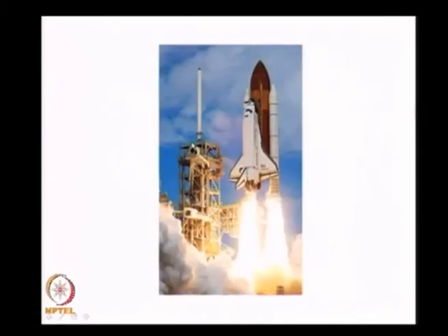At the bottom on the right hand side, the opening opens out, some flame comes out, and when this flame comes out, it hits against one of the attachments which is attaching this to the main rocket, and that gives way, and this fellow comes out and it gives a thrust in some other direction. Not only that, this flame hits against the hydrogen tank which is available in between, spills the hydrogen. This happens at a height of around 14 kilometers, and well, what could happen? Well, there is a huge fireball and the entire mission is a failure.